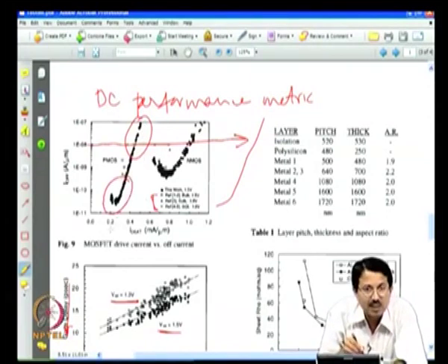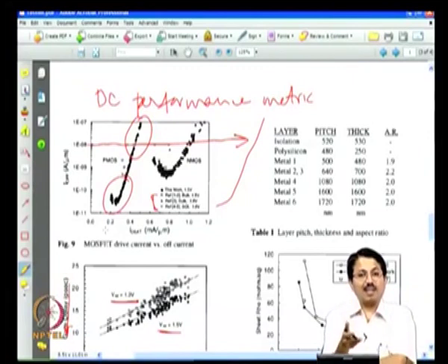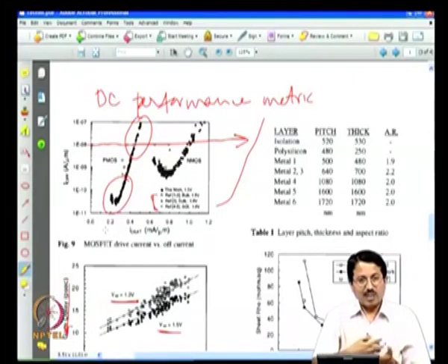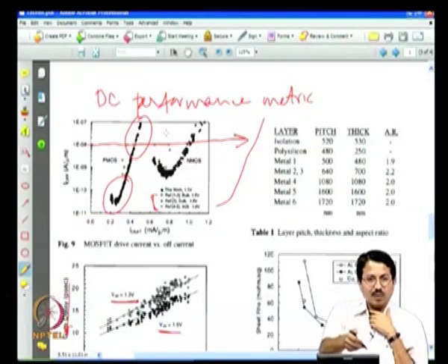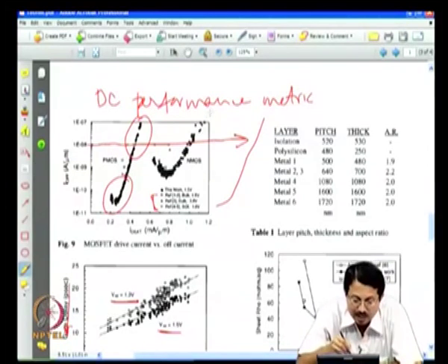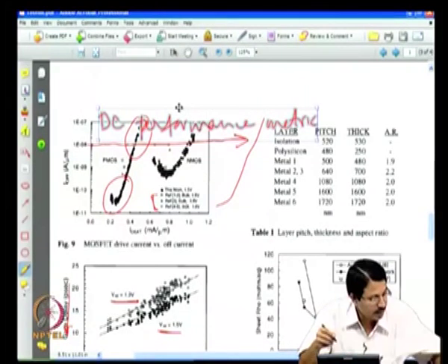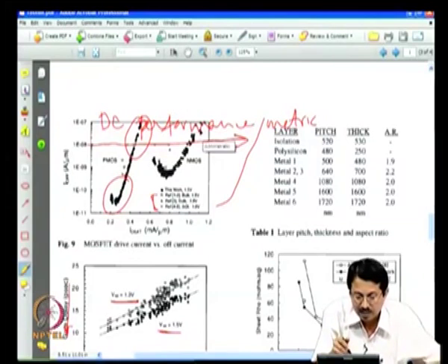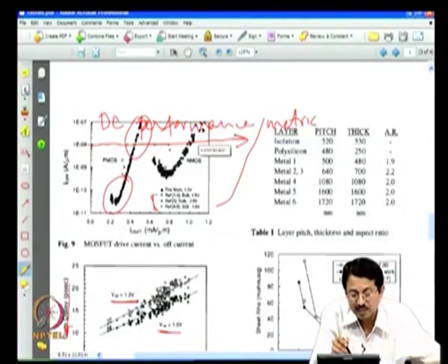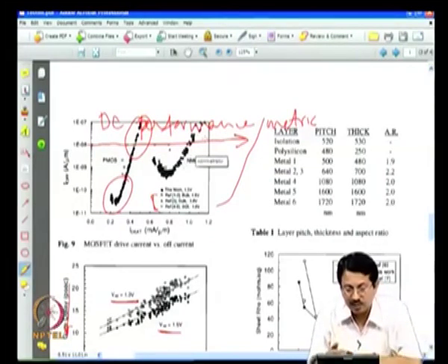All these points here correspond to a longer gate length p channel transistor, and that is how you generate a series of these points, by characterizing transistors of different dimensions and plotting a universal curve, which is an off current versus on current curve. Similarly, for n channel transistors, these are the transistors which have very high on current and off current, coming from very short channel, 130 nanometer kind of transistors, whereas along this are longer channel transistors, and that is how this is generated.